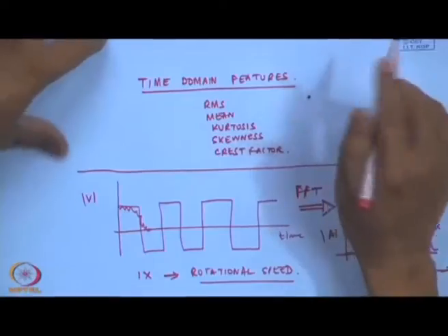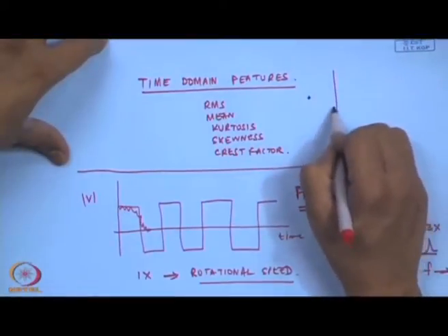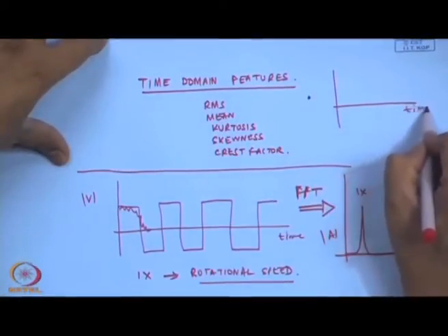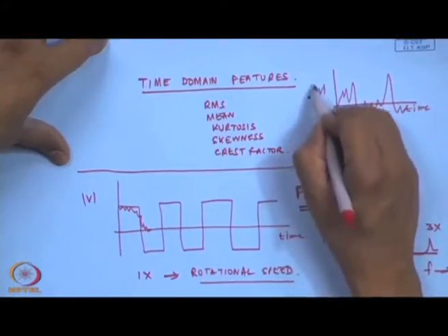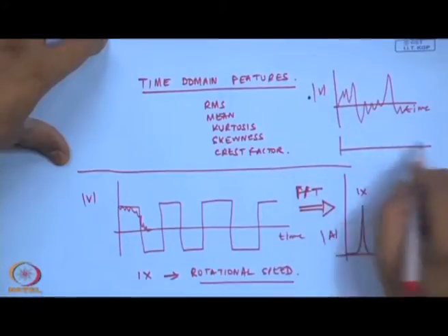If we have no idea about the speed of the machine, that is good to follow. However, wherever possible, try to install a rotating speed measuring device like a reluctance probe, an optical tachometer, or a laser based system, so that whenever you are measuring the vibration, you also have the corresponding RPM trace.